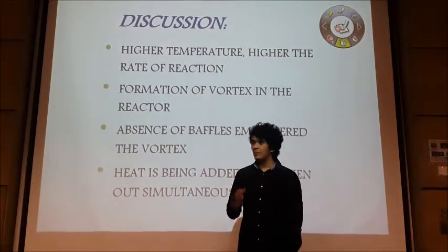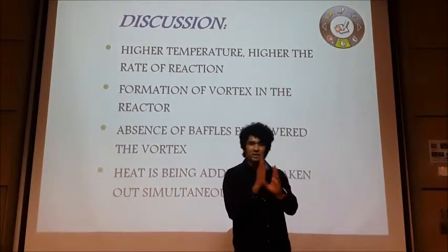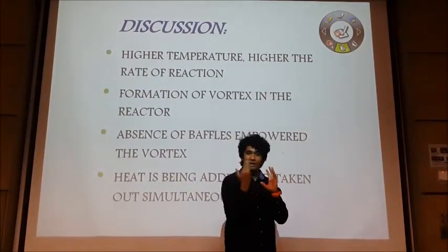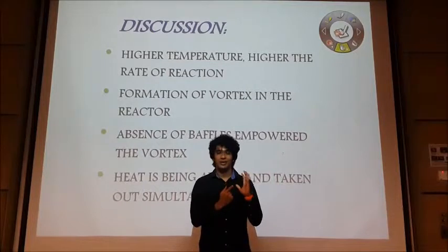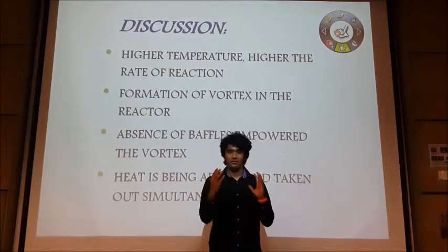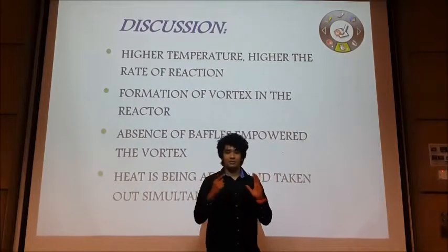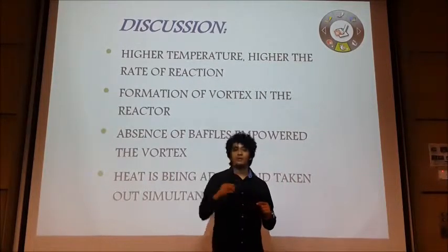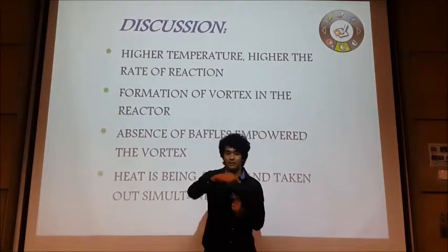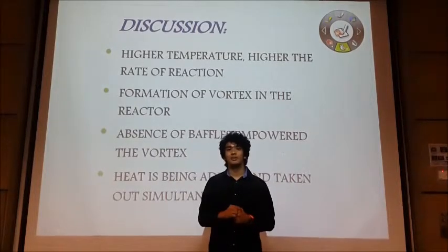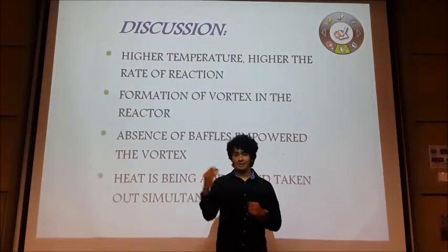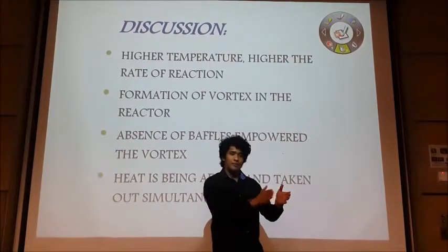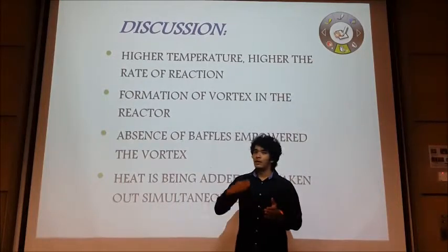Now, a vortex will actually push the particles to the walls of the reactor, so the particles on the outside will not react. That's the meaning of a vortex. Furthermore, a vortex will make the angular velocity of the particles different according to how close they are to the stirrer. This creates the pushing effect of the particles to the glass wall. Next.